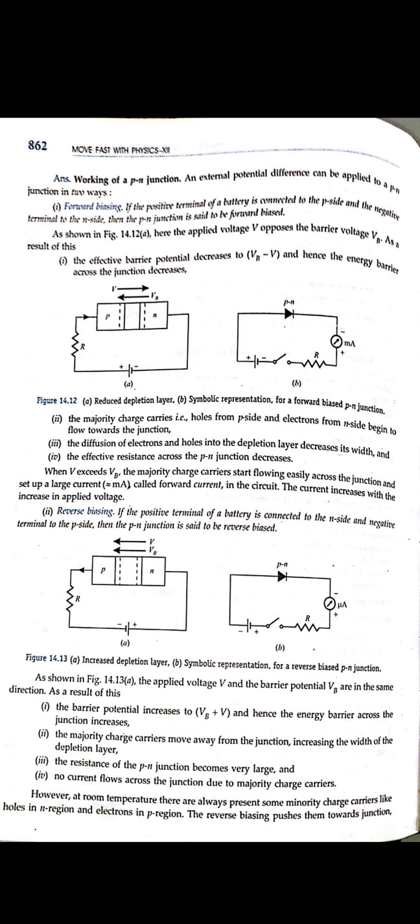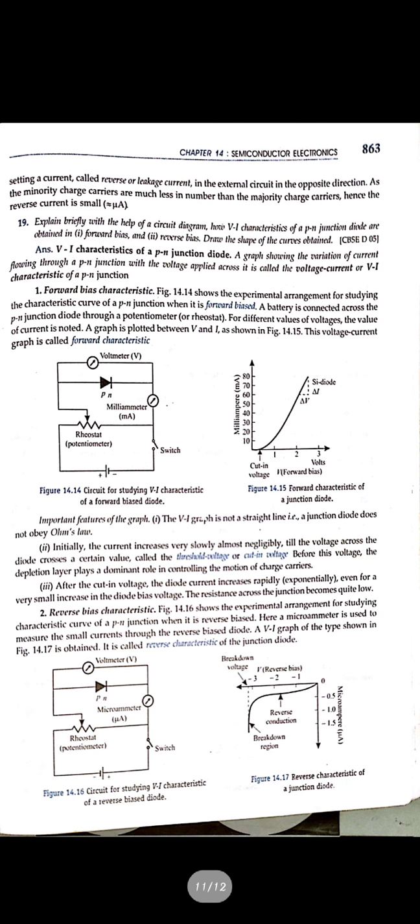At that time, the electrons get repelled out by the N type in the forward bias, but here it will get attracted, due to which the width of the PN junction layer, that is the depletion layer, will be increased. That means the barrier potential will also be increased, due to which the current will not flow. Resistance will get high, due to which the majority charge carriers cannot flow through the junction. But the minority charge carriers which are generated due to thermal generation can give the current, and that too a very feeble current, which is considered in the range of microampere.